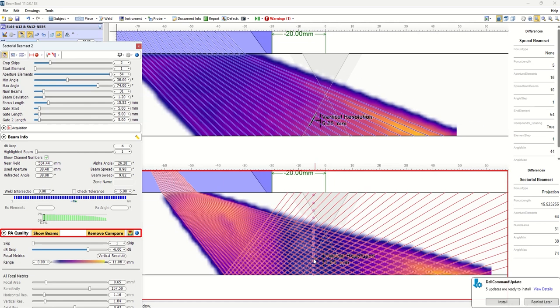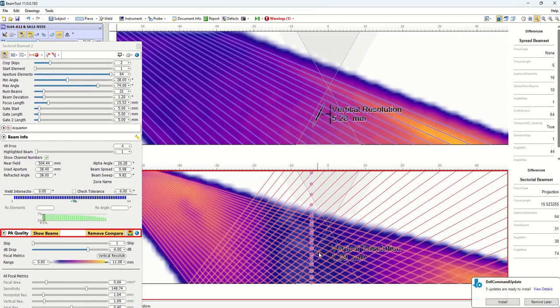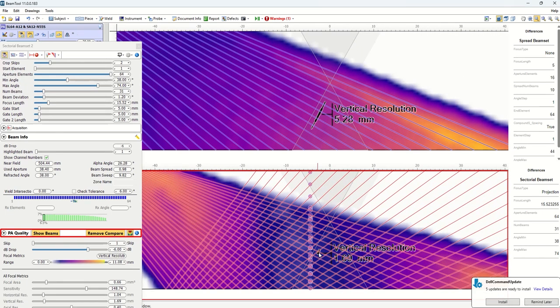And now, going forward, in the next examples we want to keep using point spread function to show you that this can open up opportunities to use focusing and assess the improvement we can get, but also be aware of how our sizing and sensitivity change outside of the focal area or zone. As you see here, if we go past our focus to the left, the size of these blobs starts to become similar because we are no longer using the focus.